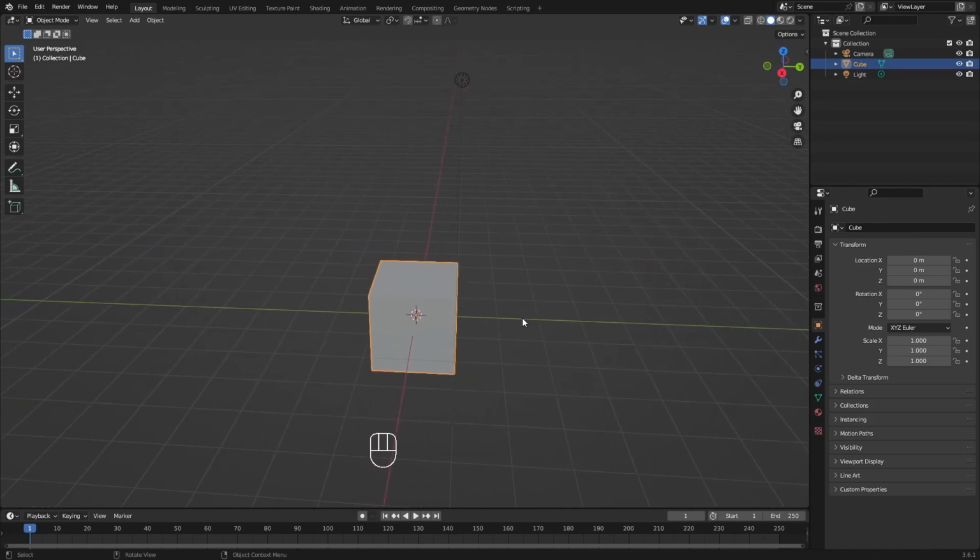In the case of people that are emulating it, you will have to do all these things, but also pressing Alt. So for example, if you want to zoom in, it's going to be Alt and Control and left click. If you want to pan around, it's Alt, Shift, left click. If you want to rotate, normally Alt, left click. That's it.